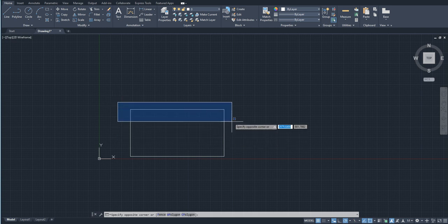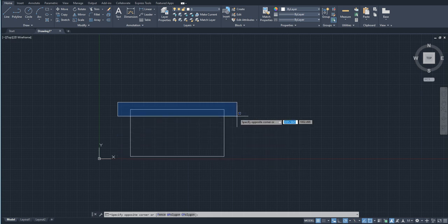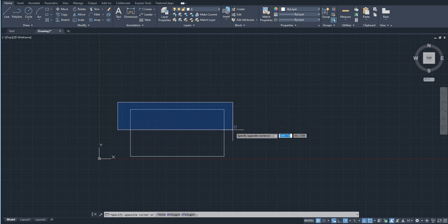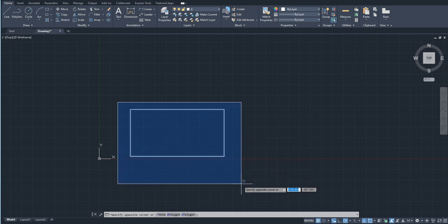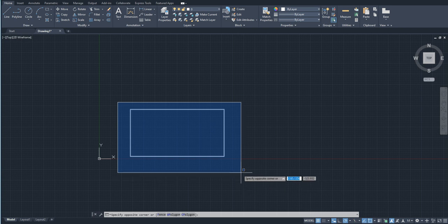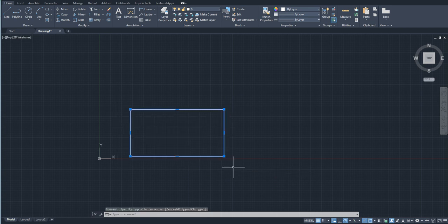You can see it's not selecting these particular lines, and that's because these lines don't represent different objects. The whole rectangle is considered as one singular object. So to select this rectangle, I'm going to have to encapture it into this blue box. If I put the whole rectangle in the blue box, the whole rectangle is going to get a bit highlighted, and if I click on it like this, it's going to get selected.